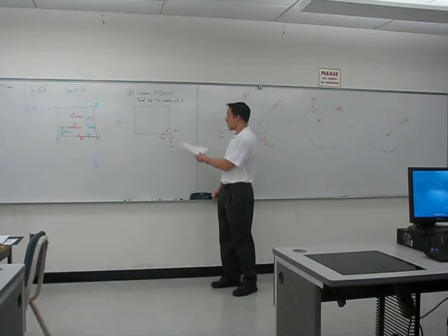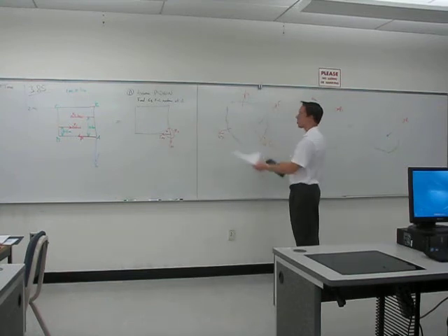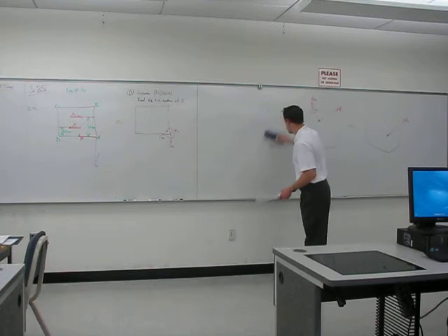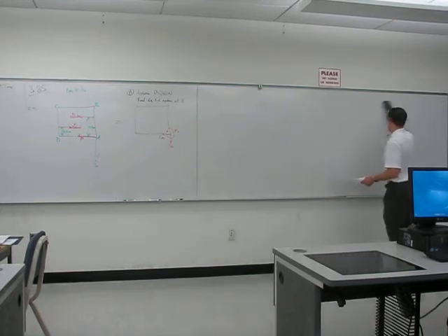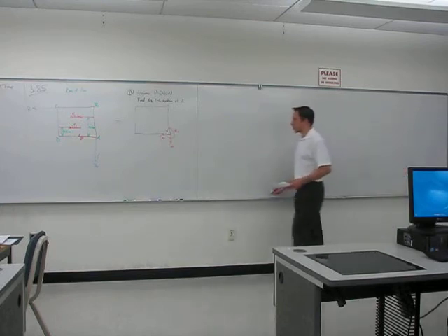Now, the way we actually go about finding the three pieces of the puzzle here that we need is to make use of that equal sign in between. Keeping in mind that tells us that the sum of the forces in any direction in the left-hand picture equals the sum of the forces in the same direction in the right-hand picture.